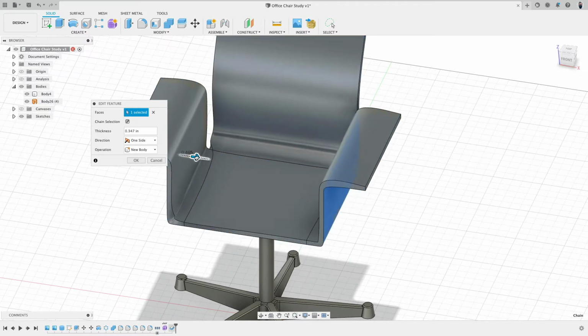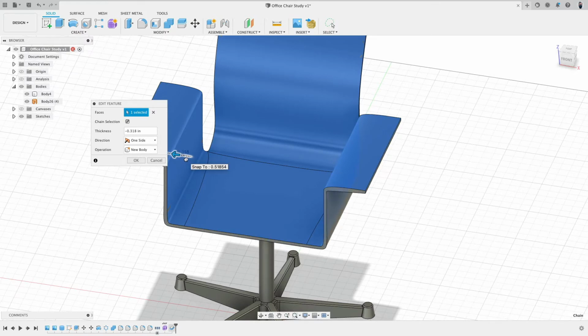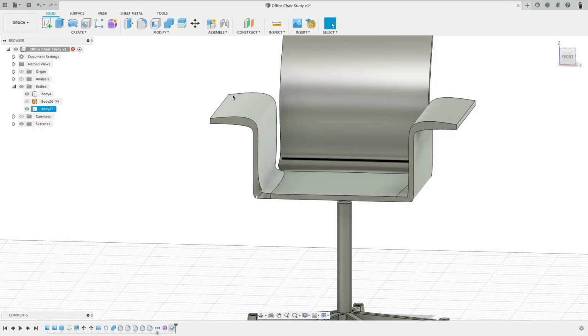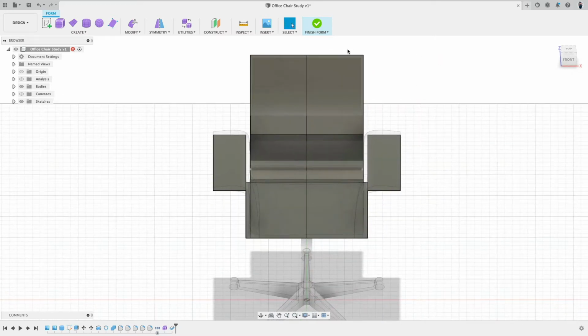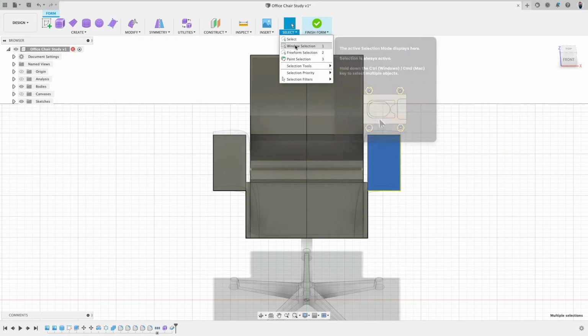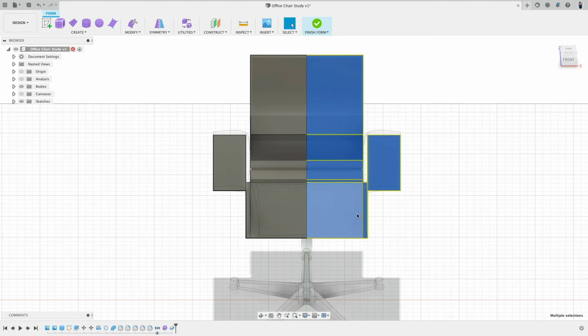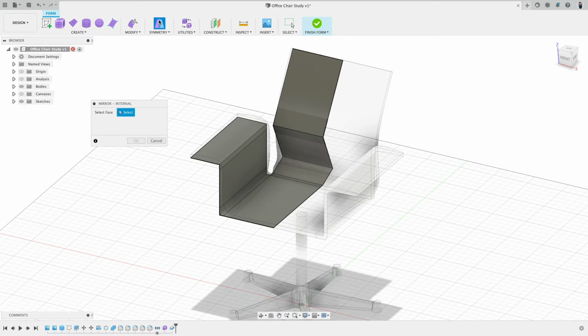So to the inside is actually not really good. You can see how we get these stretches because we have a very tight corner, and then because we create a thickness, we are tightening these corners. We can also see here some issues. So what we need to do there is we double click, and here's a little trick. Left, what's going on here? There. Left click right to the left side. Delete. No problem. Don't freak out.